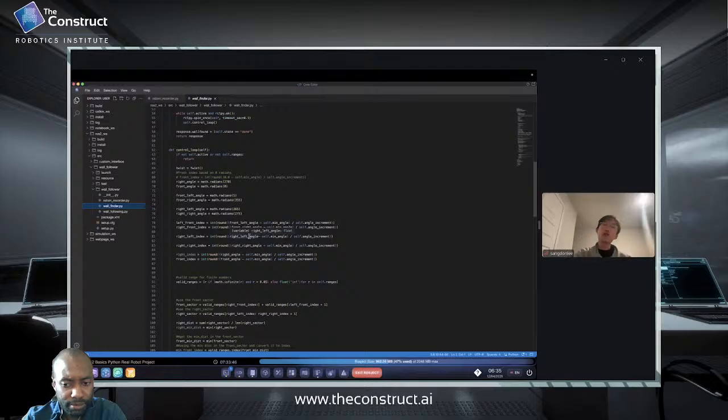And you want to have different callback groups for your subscribers and your servers, like actions and servers. Can you explain in more detail why it is important to have them in separate groups? Because when you're sharing the same values, for instance, we're using the lasers and the ranges of the lasers, you're going to have a laser callback and you're going to use the information in your server loop or action.